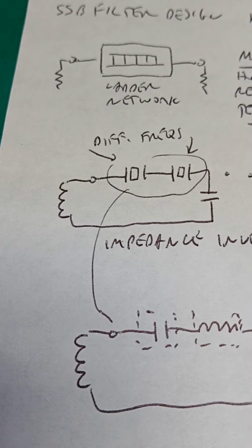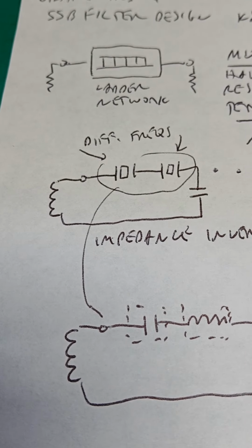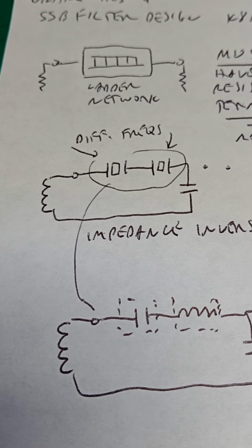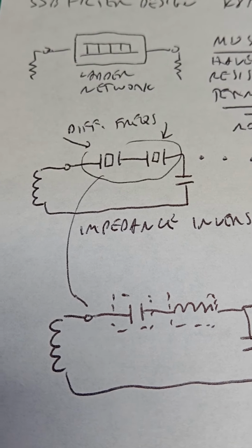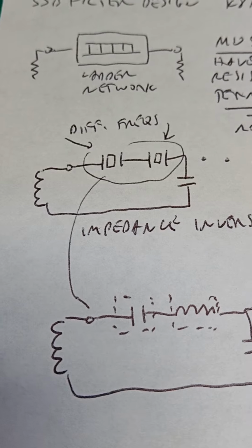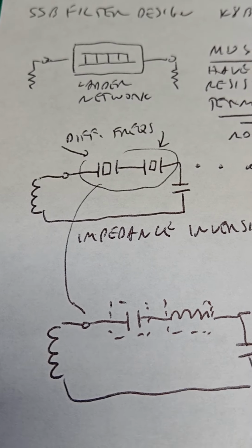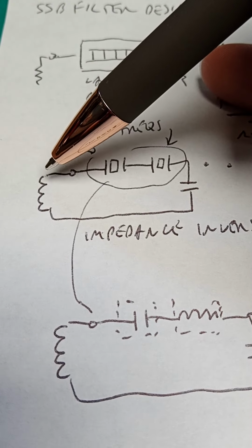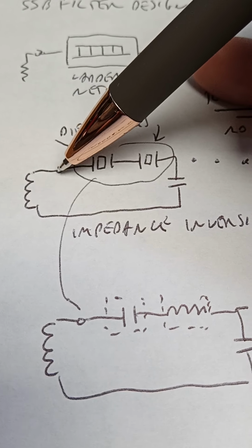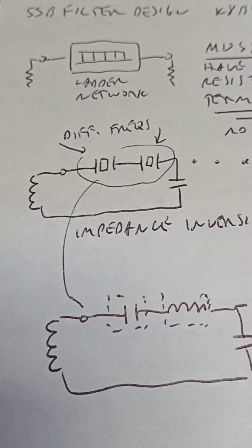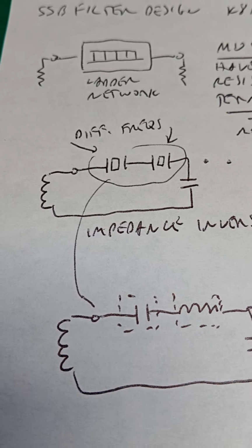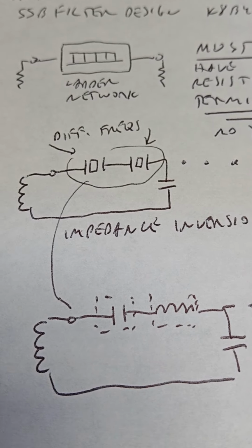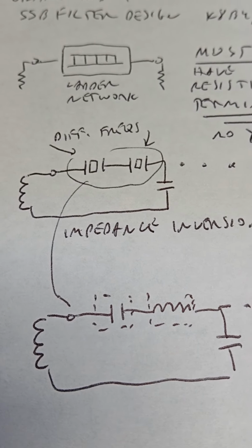Here's a partial schematic of the TR4 filter, one half of it. There are components missing here. There's a transformer, a capacitor, and 2 crystals missing, but this shows a basic point. The filter works by having a transformer winding coming in. This node is reactive, not resistive. The 2 crystals are on different frequencies, separated by maybe a kc or whatever.